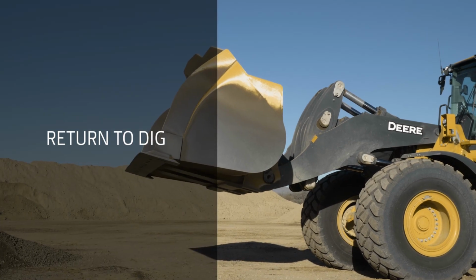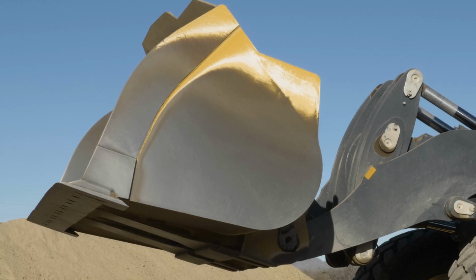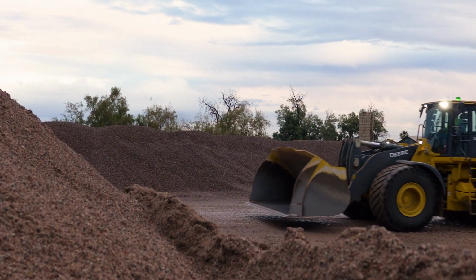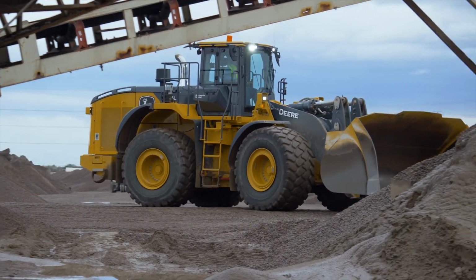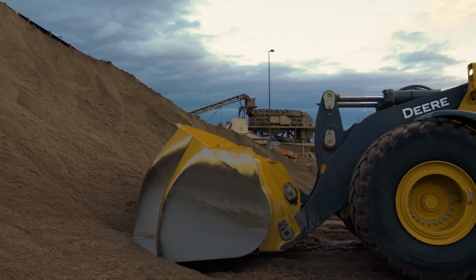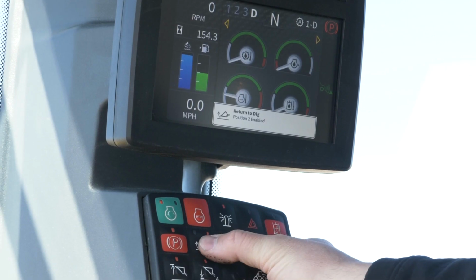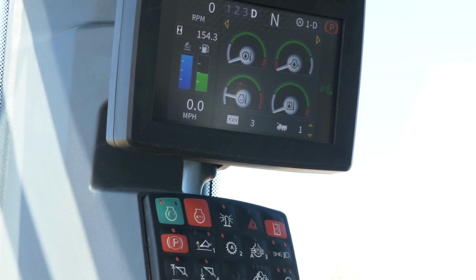With the push of a lever, return to dig restores the bucket to a preset position. Bucket and fork attachments can be leveled from either the dump or curl position, smoothing operation and helping reduce cycle times. 2 return to dig settings can be programmed to any position through the sealed switch module, SSM. To adjust the return to dig setting, place the bucket in the desired position. Then press and hold the Return to Dig button until it beeps to store the position.